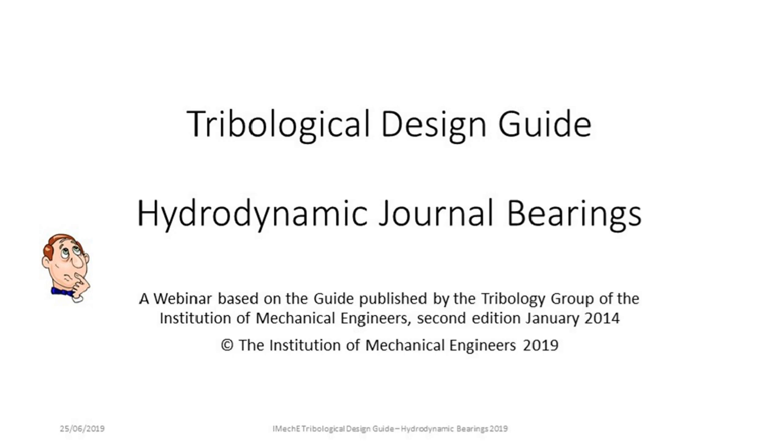I think there's an assistant here regarding the question on spiral groove, and it's saying that maybe to help on the spiral groove question, modeling of spiral groove bearings is normally steady state, i.e. hydrodynamic. Squeeze film contribution is from transient effects such as vibration, and normally very small in comparison to hydrodynamic effect.